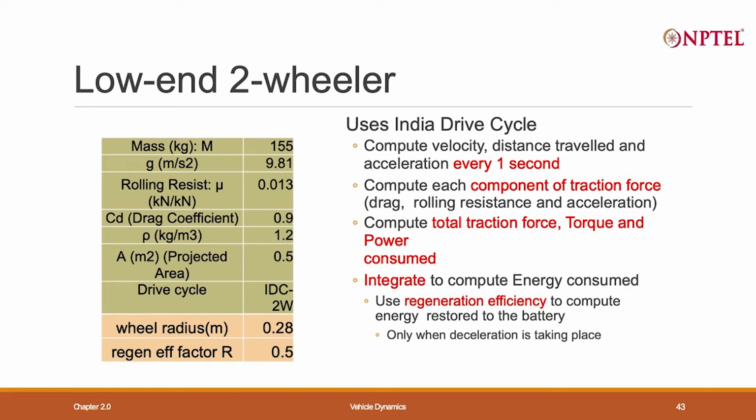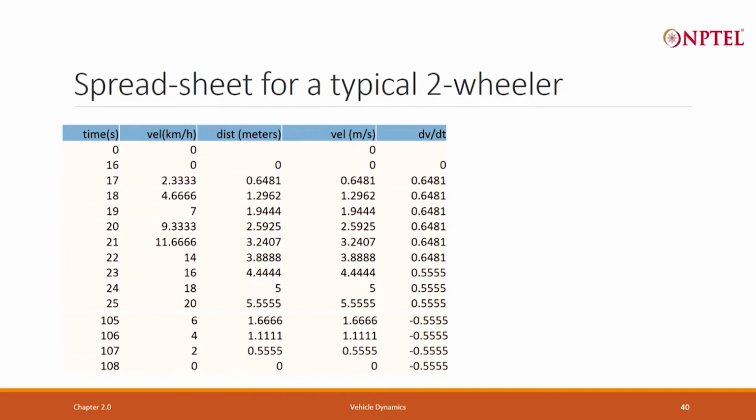And based on that, use India drive cycle, compute velocity, distance travel and acceleration every second, compute each component of traction force, drag, rolling resistance and acceleration, compute total traction force, torque, power consumed, integrate the power consumed to compute the energy consumed, use regeneration efficiency to compute the energy restored to the battery only when deceleration is taking place. So, this is the kind of spreadsheet that you create.